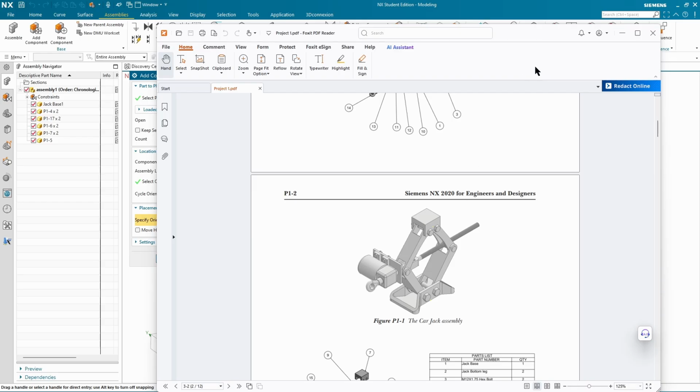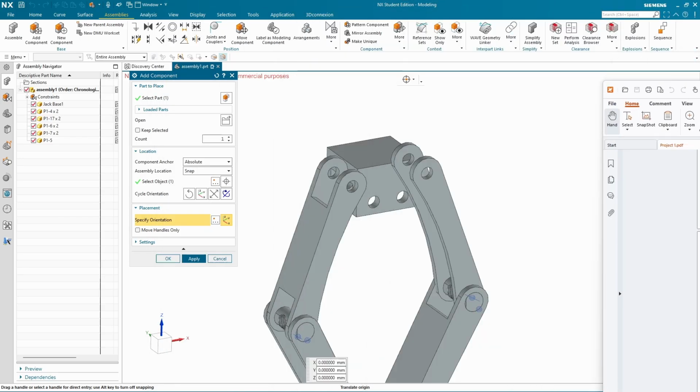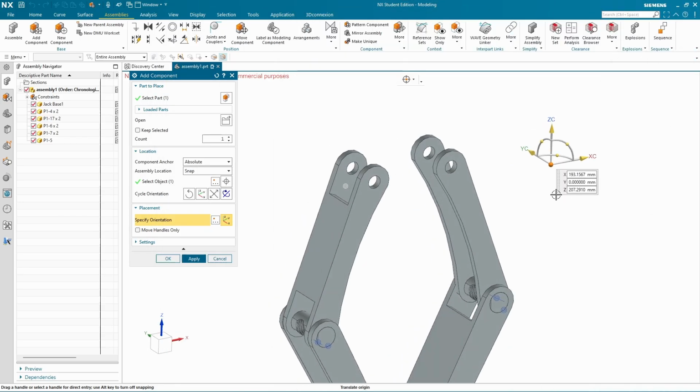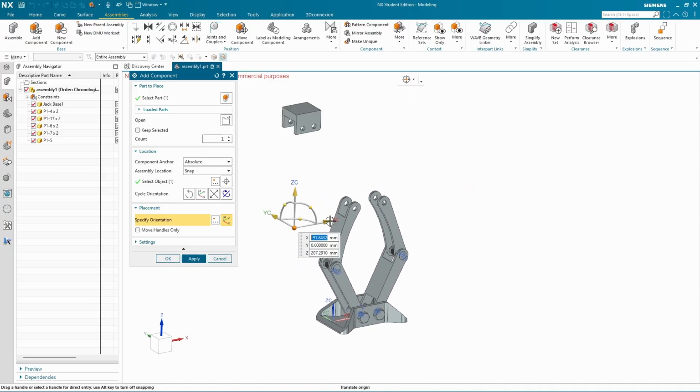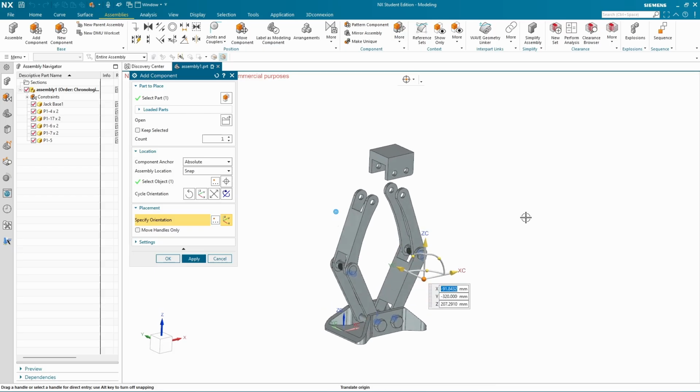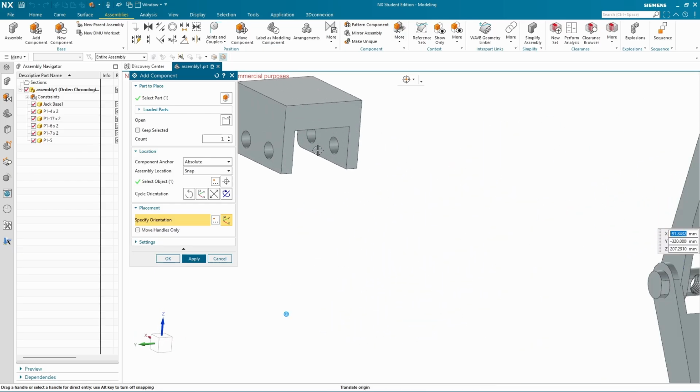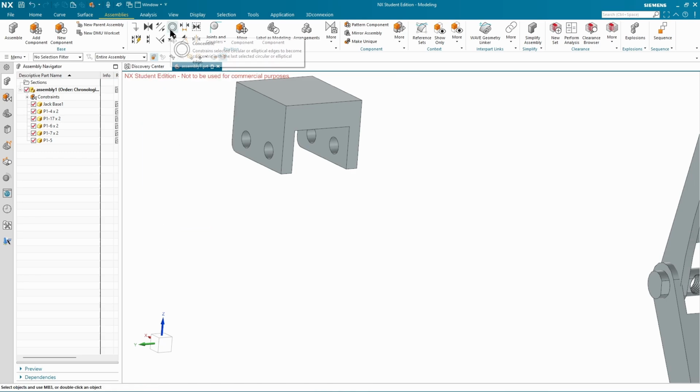So we're going to match up the inner edge, inner circle. Oops. Where'd it go? Come back. We can use this guy and get him back in a kind of close to the orientation. All right. So now we want to click on that inner circle right there. Click OK. Concentric.